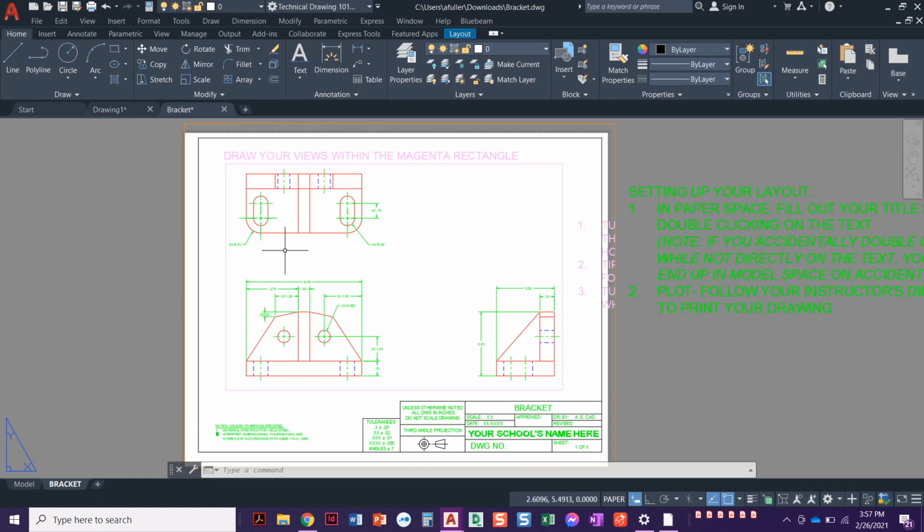What we're doing is we're telling AutoCAD, it was set to 1. It's like, oh, PSLTSCALE, it's set to 1, it's on. You've made your viewport so small I can't even see that those lines are dashed anymore. Well, turning it off says to AutoCAD, hey, I know we can't technically see those, but I made those dashed. I need them to show dashed. So ignore the fact that our scale is too small to show that they're dashed. So anyway, you're going to go ahead and do that.